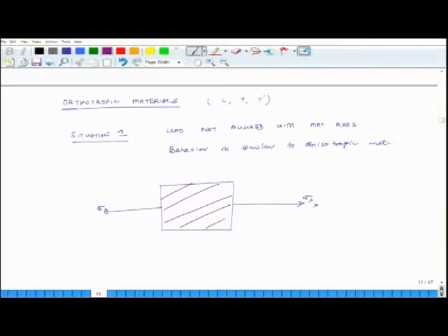The fibers are running at an angle theta, so the behavior is similar to anisotropic materials. So, this is situation 1. In this case, the response of the material is that of an orthotropic material, but this is general orthotropy.